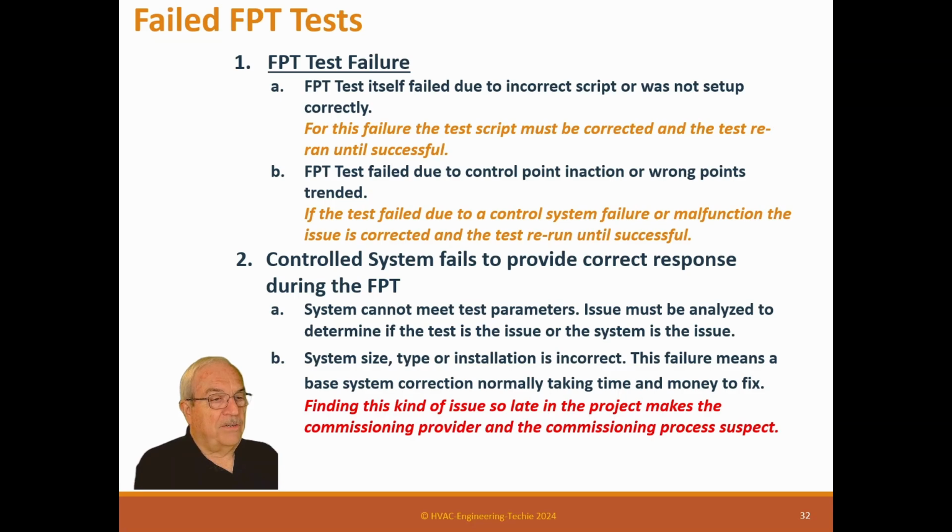I was doing a data center and I never paid attention to the humidifier for the computer room. This was a long time ago, when we had Cray supercomputers, and this job had Cray supercomputers in the space. It was a fairly good size unit, but I didn't pay attention. I never checked the size of units. This particular unit was like 10 times too big, and the engineer had it on a step sequencer. It had 4 stages of humidification because it had electric calrod heaters that brought on steam, and they were large, big kW apiece.